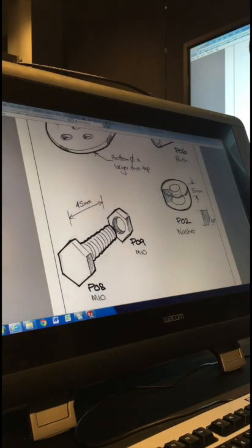So I'll grab the line tool. I'm just going to start clicking up here. Now it's important, if you think about this shape, that where there is the center area, our construction line starting here in the middle, if I start this shape here, also in the middle, when I revolve it, there's not going to be that hole. Does that make sense? You need to leave a gap between where your construction line is and this new segment, so that when you revolve it around, you'll have that hole in the middle. So instead of starting there, I just start out to the side here.